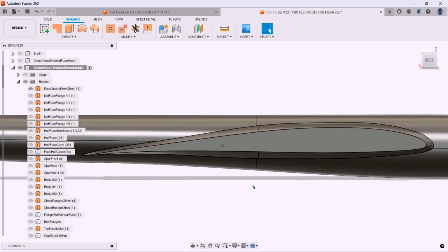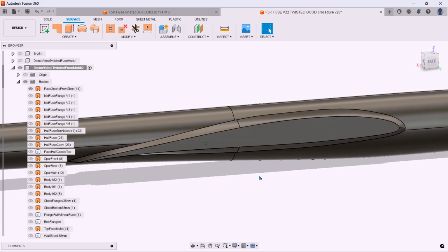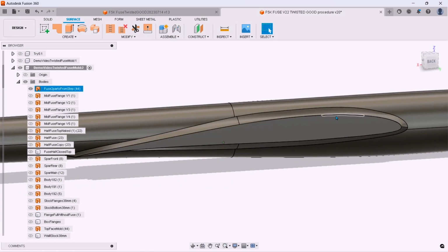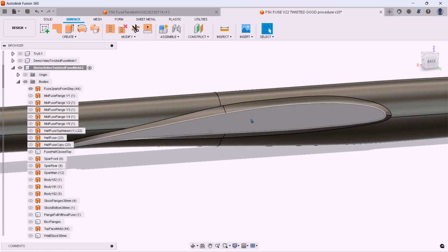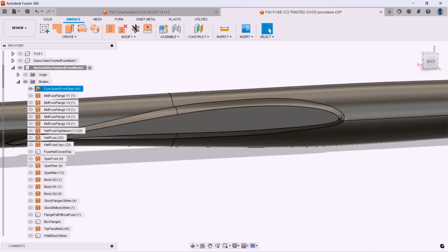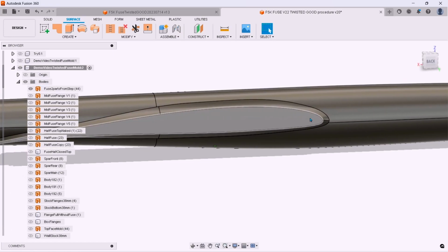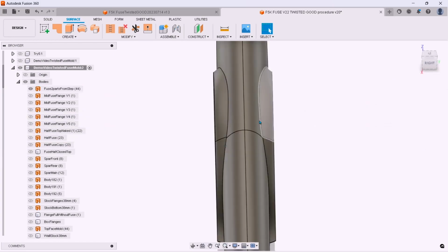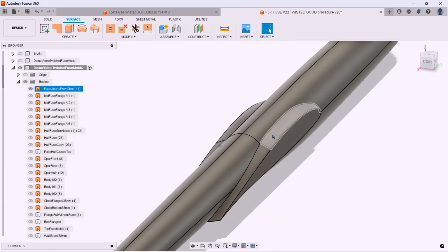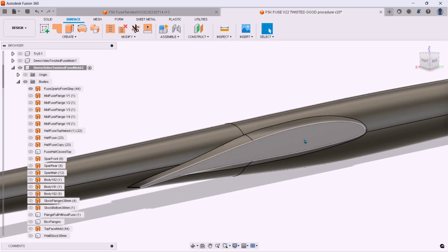And the beauty of this is, in OpenVSP you can move everything as you want. Any form, you can move the location of your command in X, in Z, the thickness and whatever you want, changing the profile. And we import all of this in Fusion 360 in a STEP or IGES file.